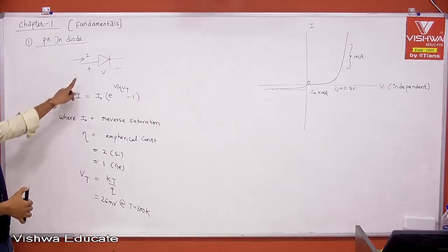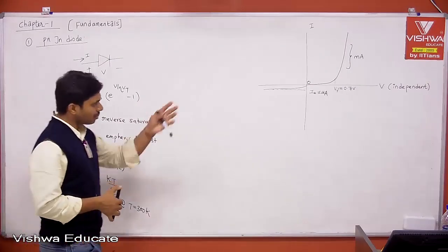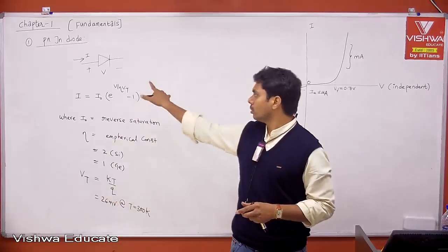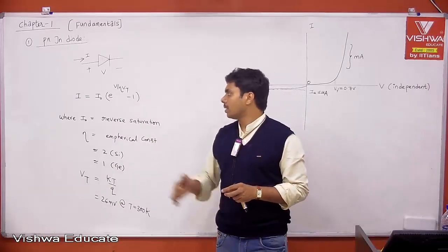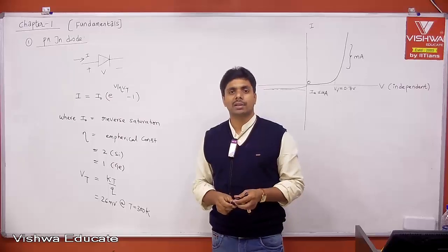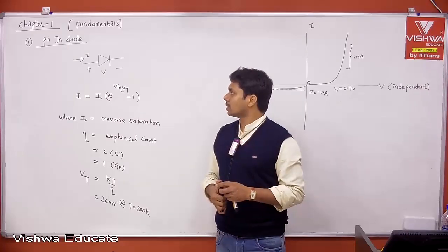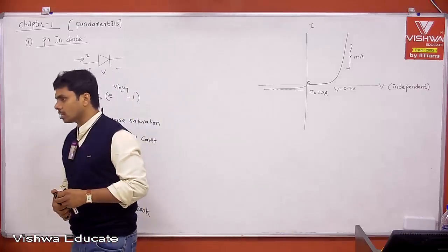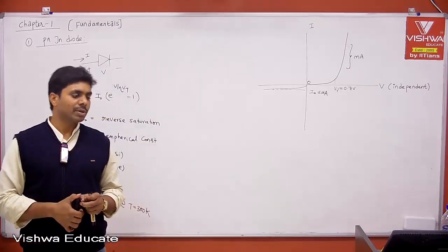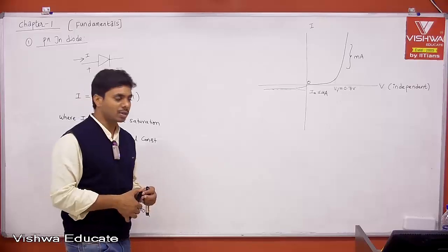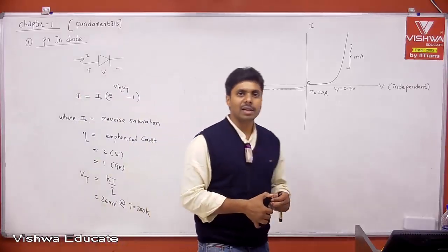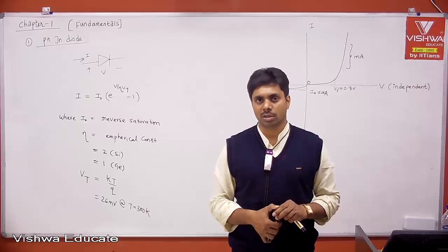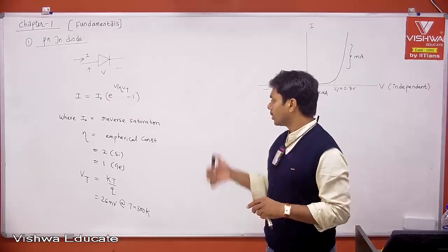But every time if you want to represent your PN junction diode like this, it is difficult. This is with respect to I is equal to I naught into e to the power of V by eta Vt minus 1, which people call the exact equation describing V to I. But people explain a few more approximations related to the diode, called diode approximation 1, approximation 2, and approximation 3. Let's see what those approximations are, and when we use them. Okay, take the graph.